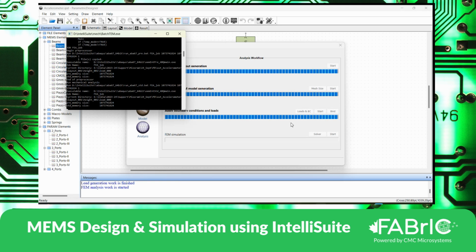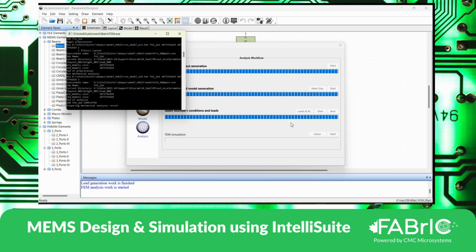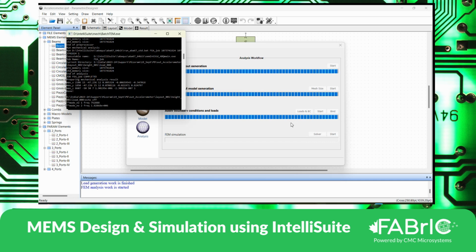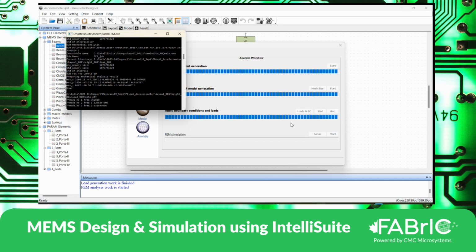So this parametric simulation, what you saw, is in terms of X and Y changes in dimension. In the case of thickness, it is not a VB script. Instead, it's a global parameter, and the thickness parameter itself can be changed, which I'll show you in the next example. Since there are 10 different steps to be completed for simulation here, maybe it would take about 2 or 3 minutes, or probably typically 5 minutes or so.